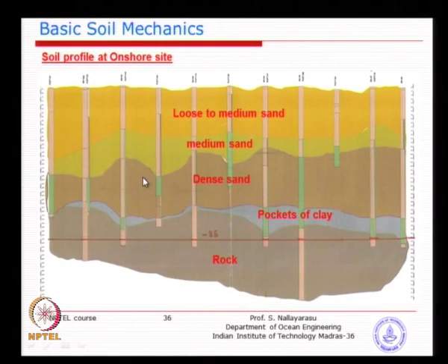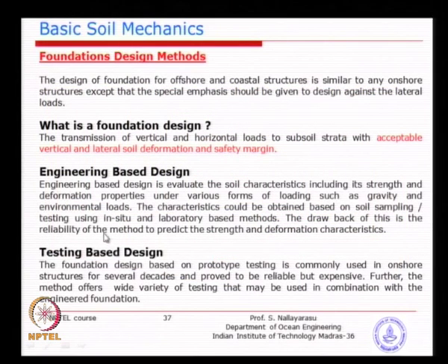One of the biggest problems for testing is the reaction. For every pile load that you apply, you need a reaction test frame, which is very difficult to make offshore. The testing we will talk about later. So, purely engineering based design is going to be a challenge, because the amount of information you gather from the site is going to be used. So, more information is better. That is where, for most offshore platforms, we rely on engineering based design, whereas for coastal and onshore structures we test, but not 100%, only partially, and then we use that information to readjust the engineering, so that we can correct the mistakes.